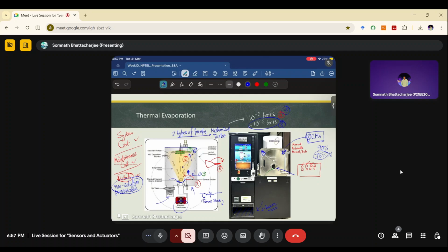No, sir. We can perform the photolithography by directly loading the mask, exposing UV, then performing hard bake. To reduce the time consumed, we can skip the soft bake, sir. That's based on how much detail you have in your mask itself. If you don't have very fine details inside your mask, it's best to use the hard bake directly.